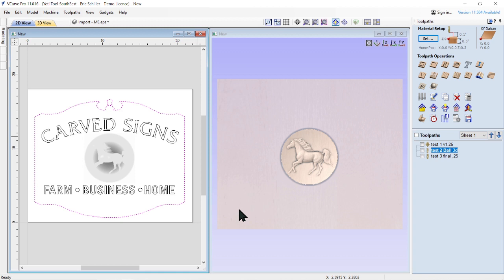And then we're off the thickness of the paper. So you can either change the depth of cut, or you can move it off of the material, tell it to go to Z0, and then using the center of the jog wheel, convert it to 0.1 millimeters and go down another 0.1 millimeter. But in this case, he was having flat spots.